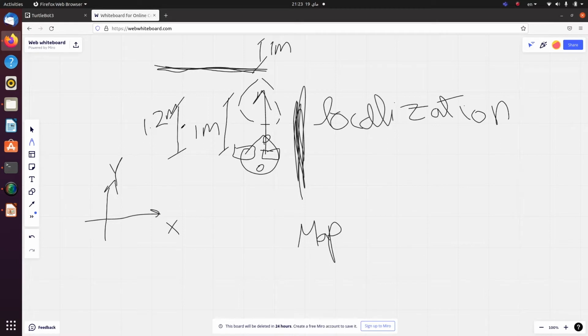So the IMU gives a reading every, for example, 0.1 second, but the LIDAR would give you, say, an update every 1 second. Right? So you have a compromise between accuracy and speed or frequency. Alright, so it's a compromise of two things.